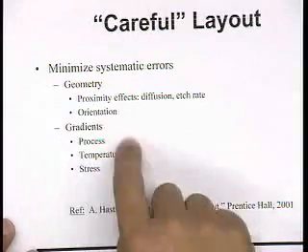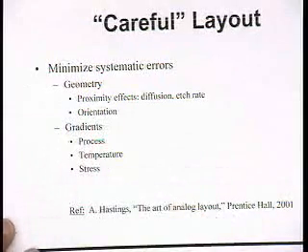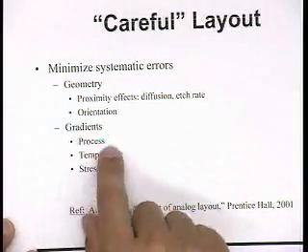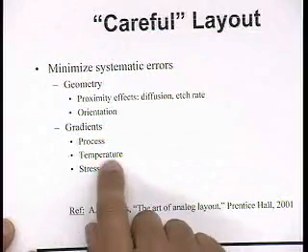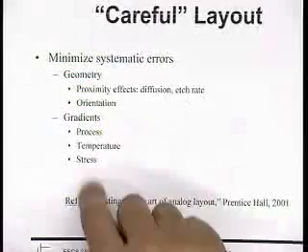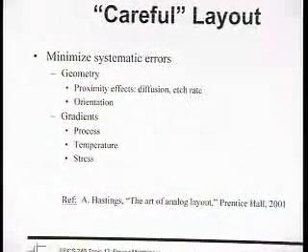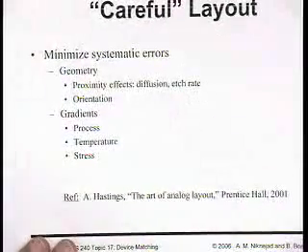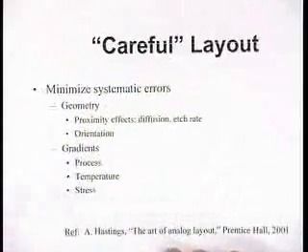I can also try to combat things like gradients, right? Process variations, temperature gradients, stress gradients, by using things like common centroid. And using these two techniques together, I can work really hard to get my mismatch down to an acceptable level.